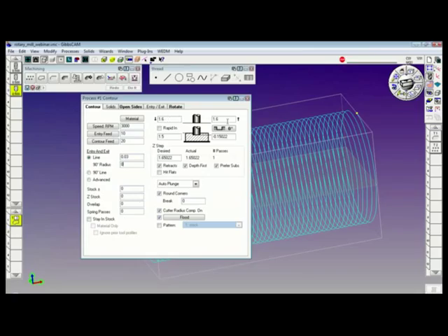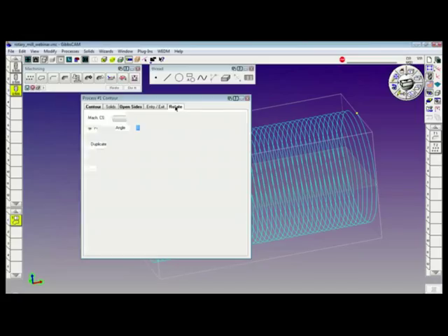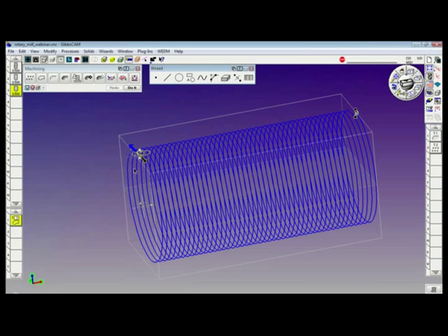My approach is still good. My top of cut is still good. My depth of cut is going to change. I only want to cut this maybe 60 thousandths deep. So once again, establish the top of the cut, subtract the depth of cut, and my desired is 60 thousandths deep. Okay. Rotate tab. This is machined in Rotary Milling. Close the dialog window. Pick the start point. Pick the center circle to cut on center.